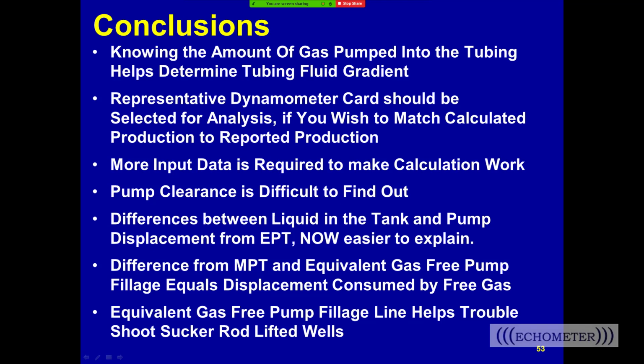So it goes from 25% constant to another pump would reduce it to 20%. So by a 20% factor. So anyway, my comment is yes, every foot increase in the pump length reduces the slippage approximately 5%. It's 1 over the length that is the ratio.